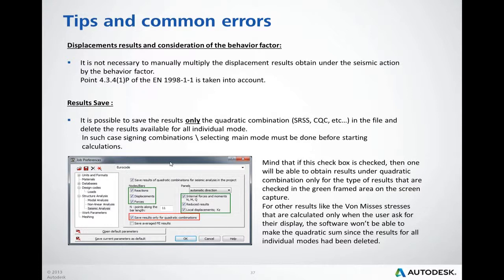It is possible to save the results only for quadratic combinations, CQC or SRSS, in the file and delete the results available for individual modes. One hint: in such case, assigning combination and selecting main mode must be done before starting calculations.